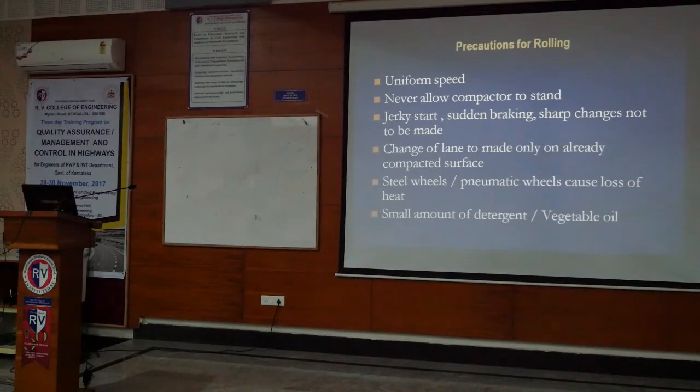So these are the most important things to be followed during uniform speed of the roller. We should not allow the compactor to stand on the hot layer, no jerky start, no sudden braking. Change of lane to be made only on already compacted surface.